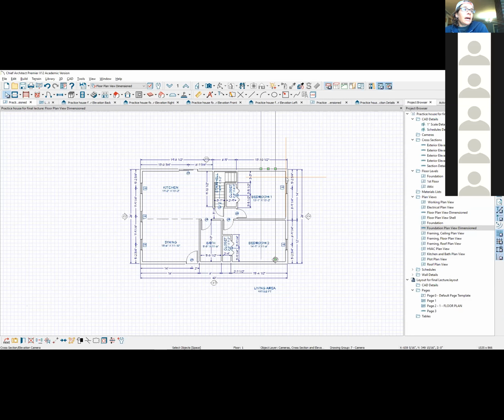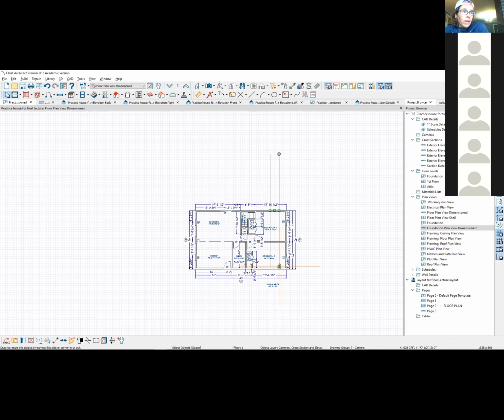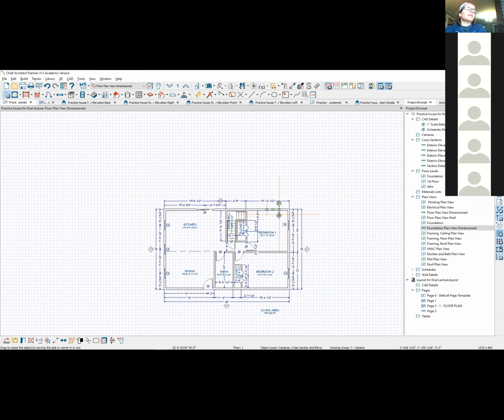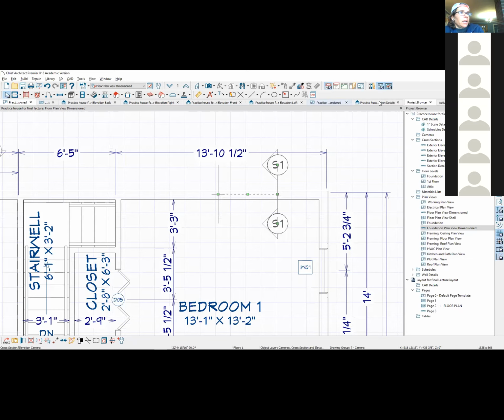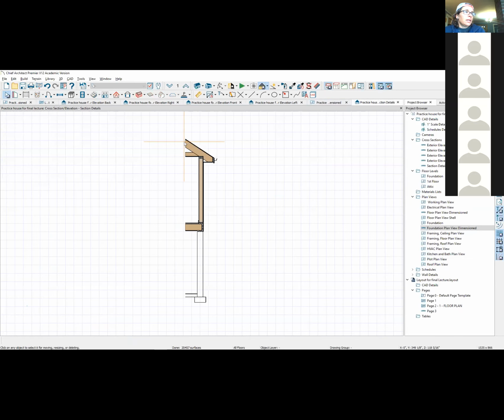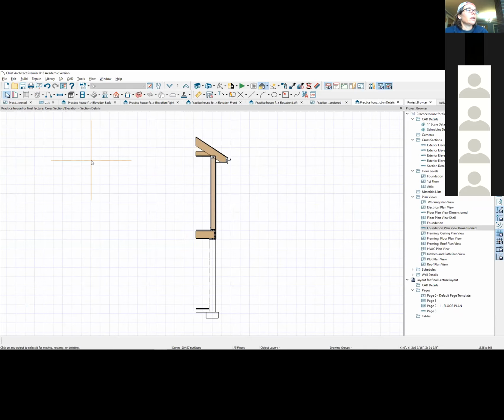And what you'll see is that we got a call out on each end of that cross section, and I can drag these in. When I drag them in, I'm setting the extents of that cross section view. So now when I look at my cross section, it's nipped off. I only have a short distance shown here. That allows me to trim this down and only show a little bit of it.